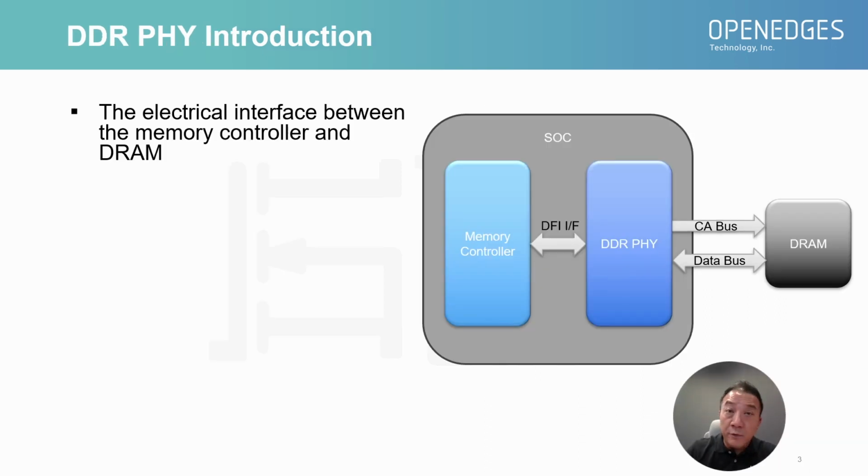So this talk today focuses on the DDR5 products, so I thought I would give a high-level introduction of DDR5 for those that are not familiar with its role in the memory subsystem. Effectively, the DDR5 is the electrical interface between the memory controller and the external DRAM. Today, the DRAM can be mounted on a silicon interposer, on a packaged substrate, soldered down on the PCB, or it can have a DIMM form factor that is plugged into a DRAM socket, depending on the DDR standard.